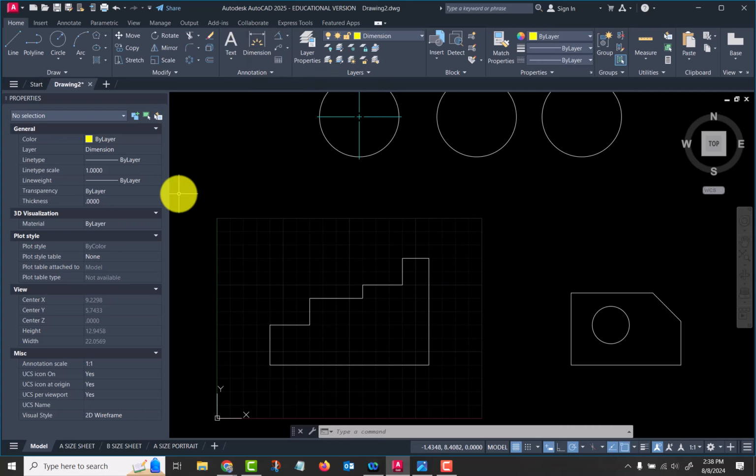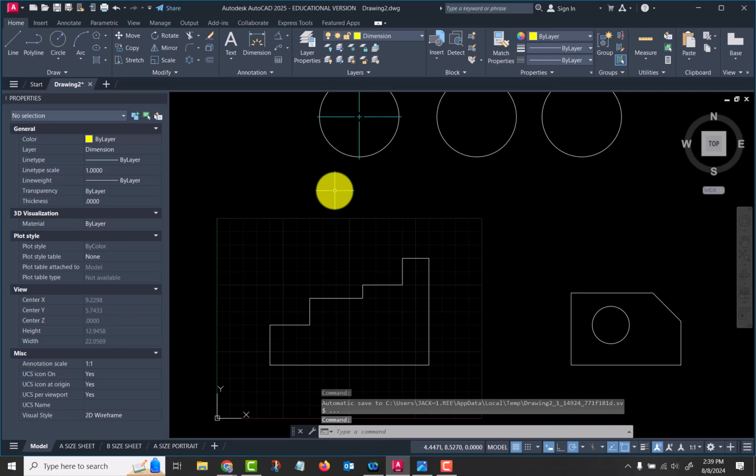The dimensioning tool in Inventor works marvelously. I don't know why the one in AutoCAD doesn't work as well. But let me show you a way that you can bring up a dimensioning toolbar. And this goes with your workspace. So if you want to save this kind of thing, it's not a by-file thing, but it's part of your workspace. So on your command line, type menu and then select menu bar.